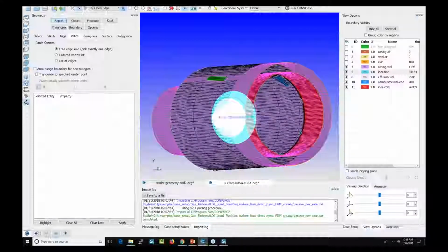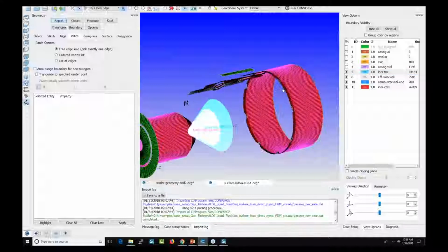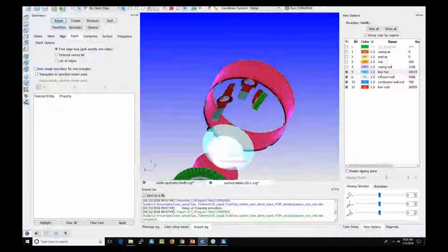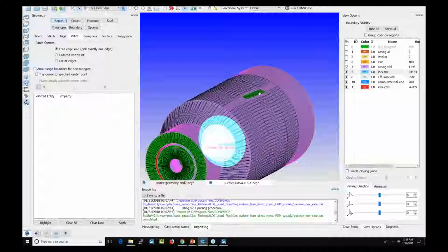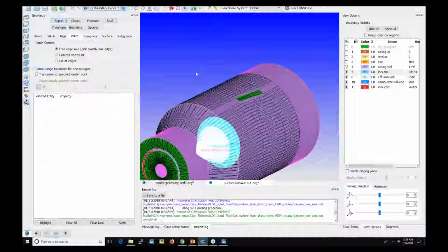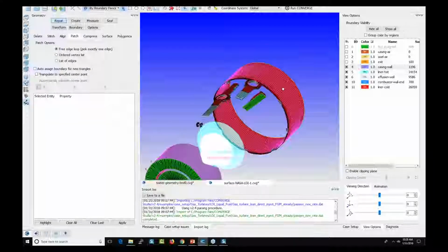Now since I've already flagged it, it's easier to look inside the geometry. You see how if I want to look inside the geometry, if I had not flagged it, it would have been tricky. Or I could have done this. Triangle by boundary fence, I could have selected these 2, right click and Hide selection. Now I can look inside the geometry.